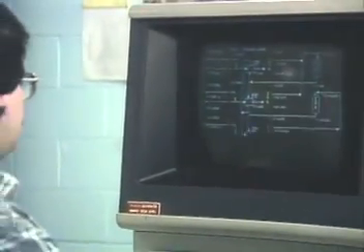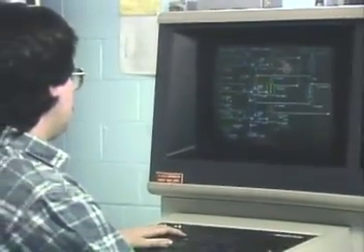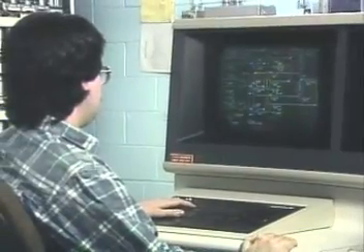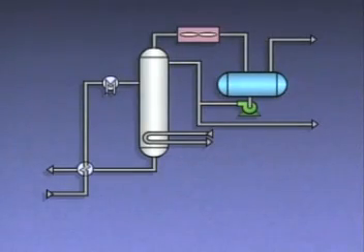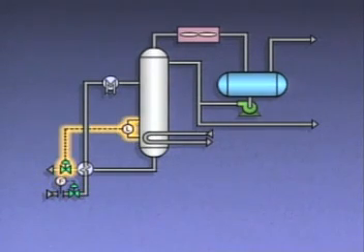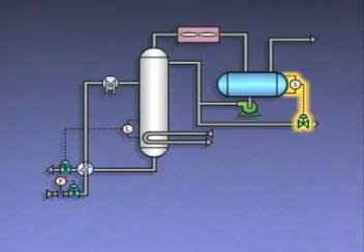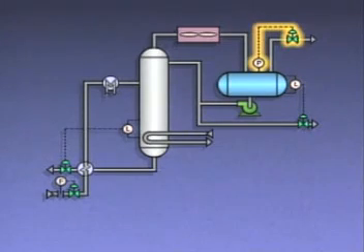The flows of materials are controlled by control loops. Control loops consist of instruments and devices that work together to monitor and control the values of process variables, such as pressure, level, and flow. Control loops are part of the distillation system's control system. In our example, the flows of materials are controlled by a feed flow control loop, a bottom level control loop, an overhead product level control loop, and an off-gas stream pressure control loop.